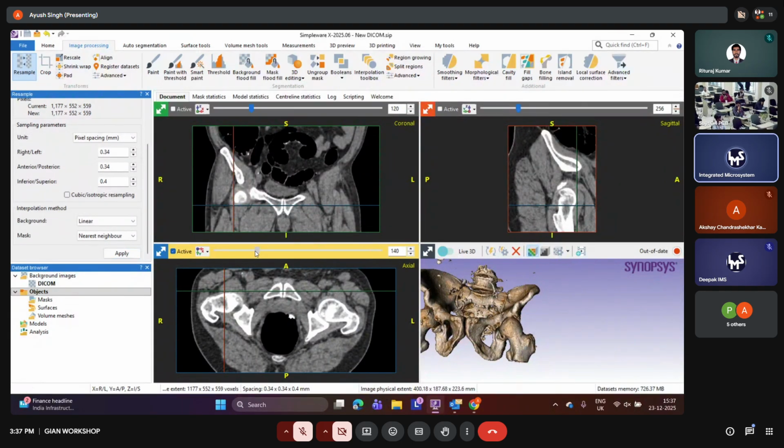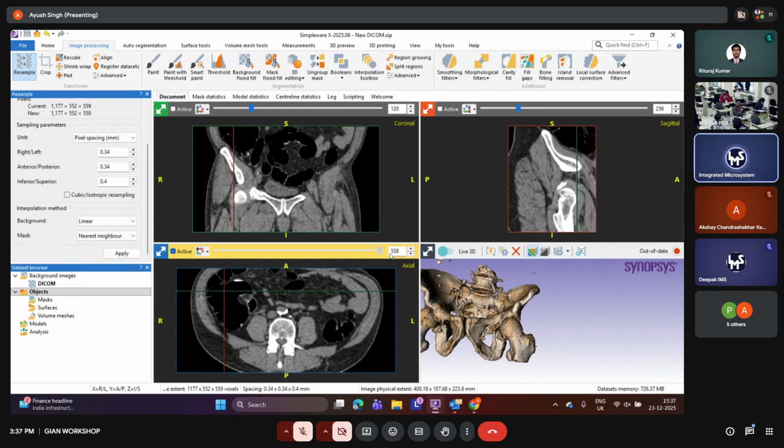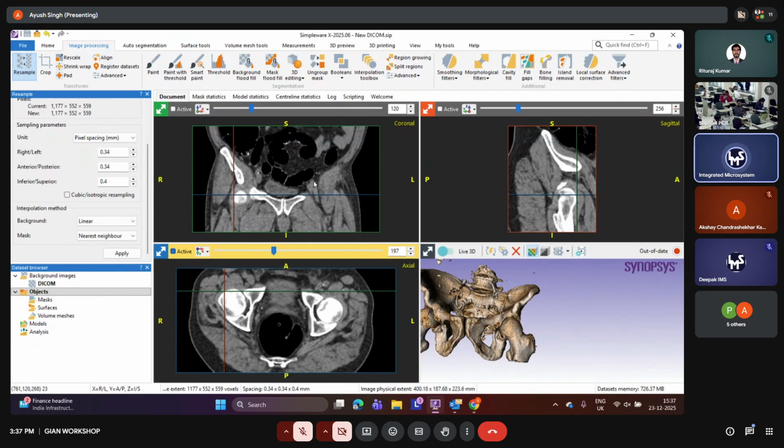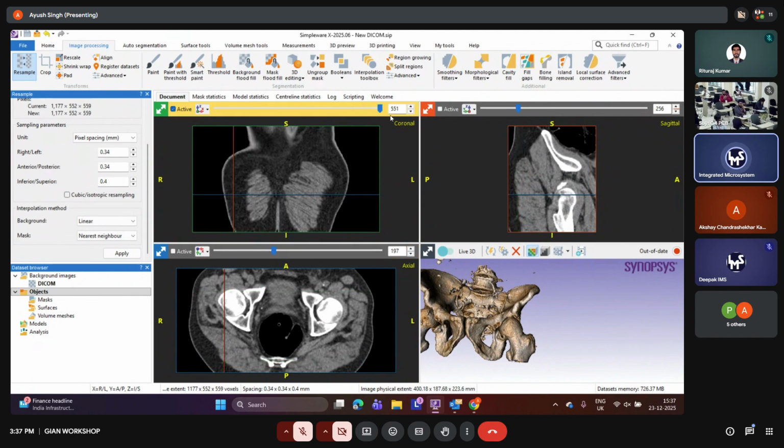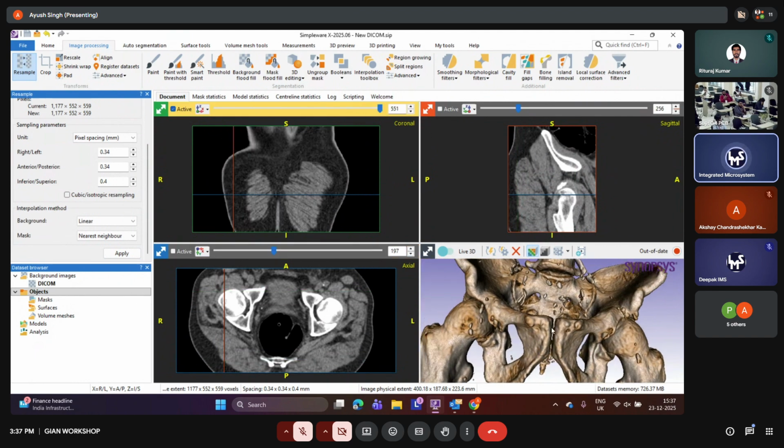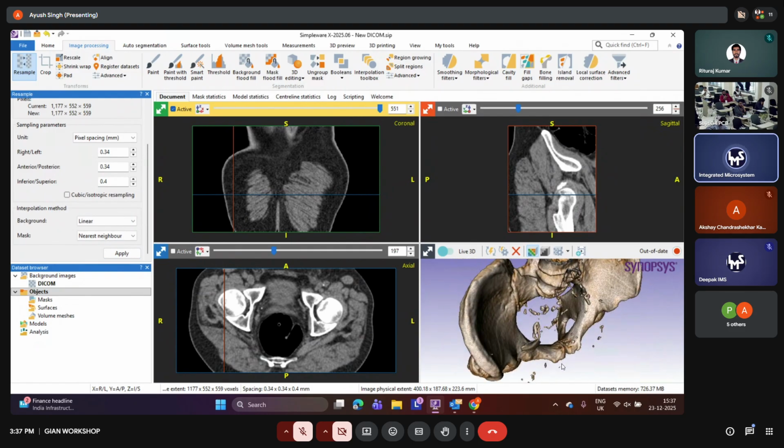What it has done is, earlier it used to have 278 slices. Now it is 558 slices in the actual view. Similarly, the number of slices has increased in the current view. So now we have a much more accurate mapping of the dataset. We can anytime resample, that is upsample, the dataset if we are doing the characterization of, for example, a porous aluminum material. Since it's also used in material image processing, we can also downsample the dataset. Once the downsampling is done, we can work on larger datasets, and datasets of around 10 GB, 20 GB can also be simulated.